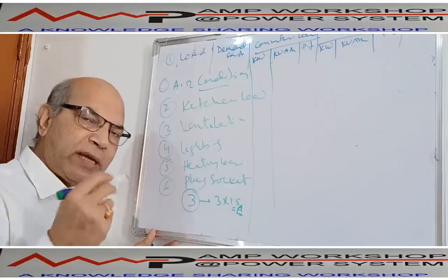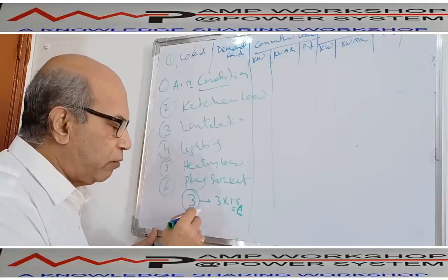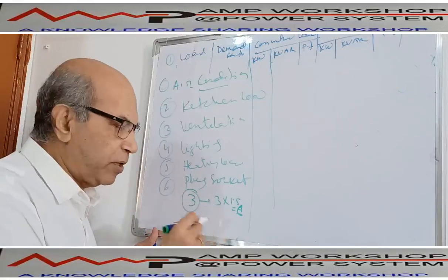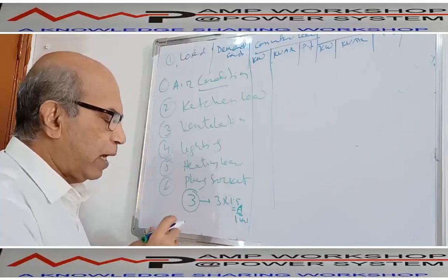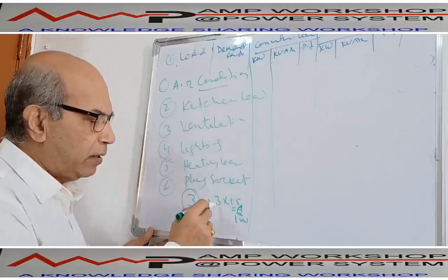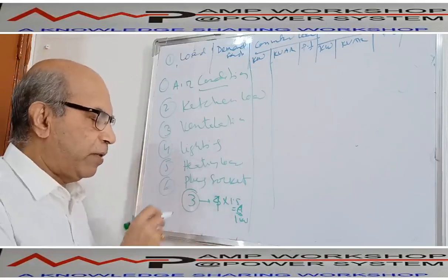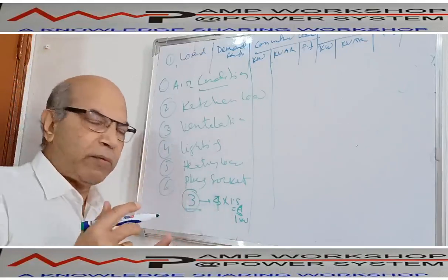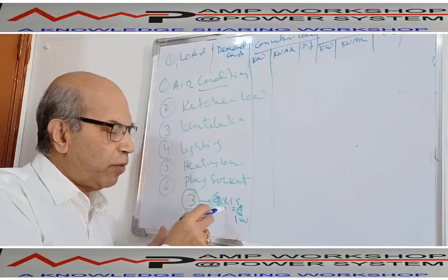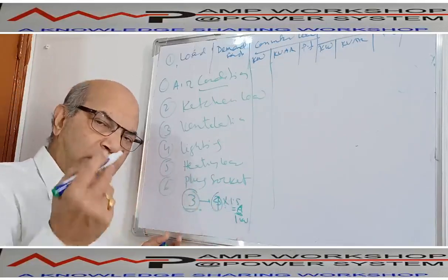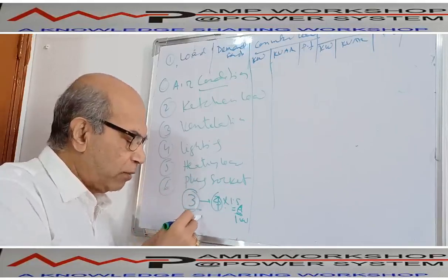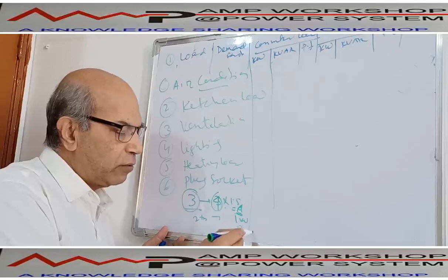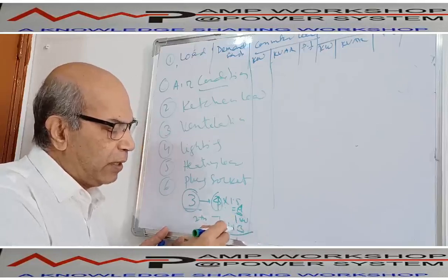Then in the guest room, 100 square feet, you need approximately a 0.8 ton machine, which is approximately 1 kilowatt. So okay, 6 plus 1, and then you have 3 plus 4, actually 4 rooms, because 3 bedrooms and the dining area is also about 150. So there are a total of 4 rooms, 1.5, 6 kilowatt, and the drawing room or living room is a big room, 400 square feet. So you need about a 2-ton machine, which is equal to 3 kilowatt. So if you calculate all this, it is approximately 10 kilowatt.